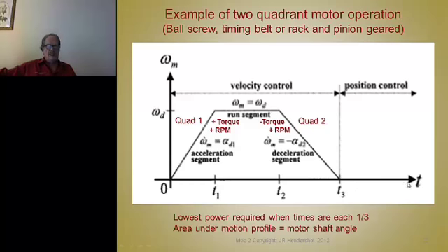You'll get some ringing due to the compliance. So you might need dampening in the circuit, which is friction. All those things taken into account. But this type of move demonstrates the importance of positive and negative torque. Negative torque is always braking torque. Same thing in a car. A car accelerating here. It's going along the highway. When you stop, you come out to this speed.